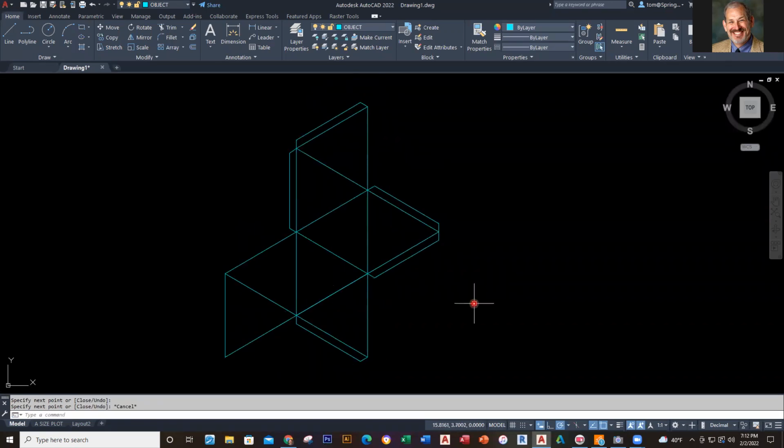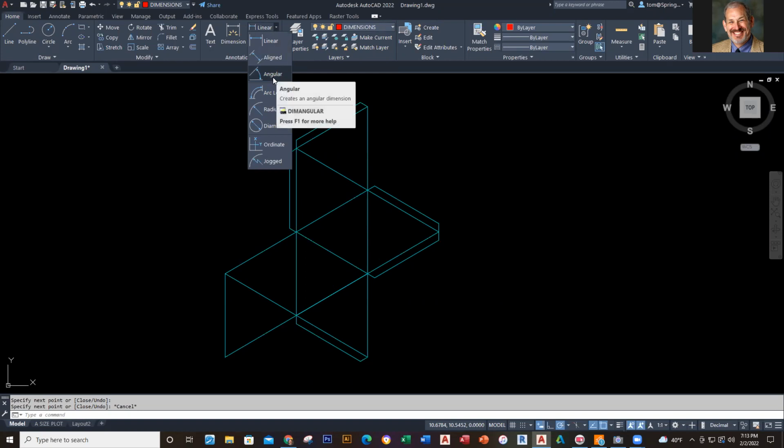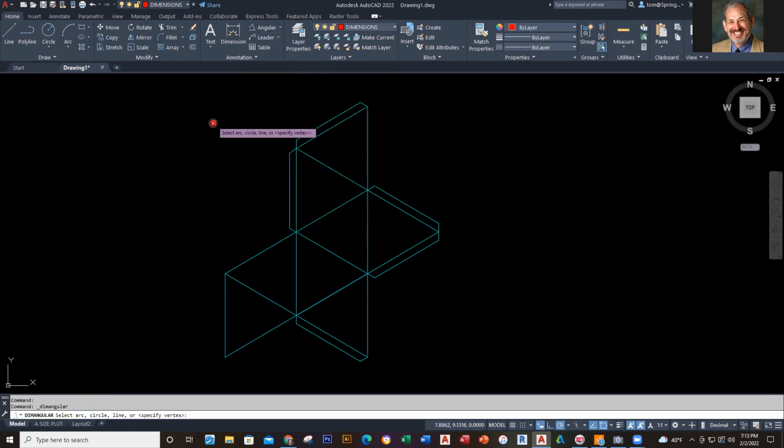And so once we have that in shape, that's looking pretty good. And at this point, we just have to put the dimensions on. So we talked about the dimensions. One of the dimensions that we have here is actually something new, and that is this one. If I go here, you'll notice that there is an angular dimension. So I'll go to angular. And when I go to angular right here, I can go ahead and pick the lines that I want to define. I go there to there, and I pull it up, and there it is right there at 60.